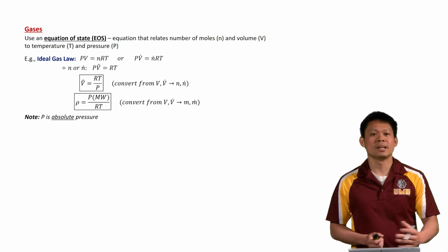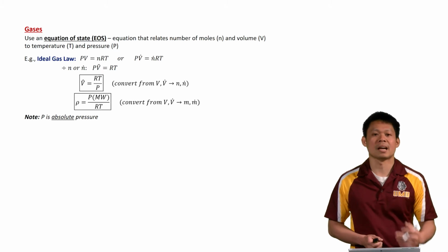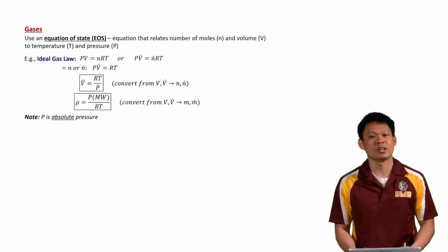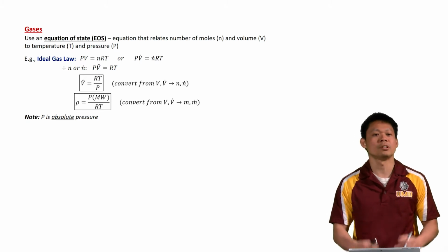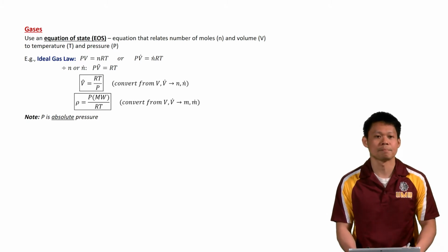Note that in all these ideal gas equations, the pressure is absolute pressure. So if your measurement is in gauge pressure, make sure to add your atmospheric pressure to it to get your absolute pressure before putting it into these equations.